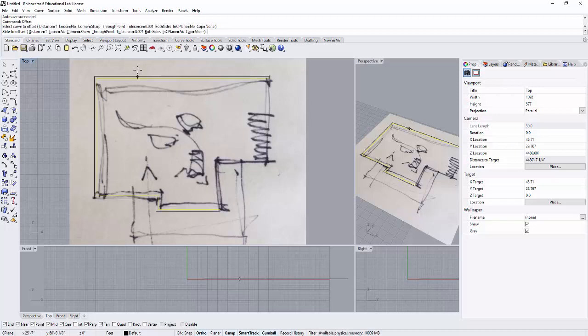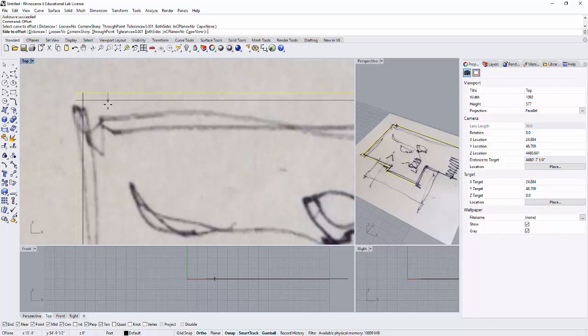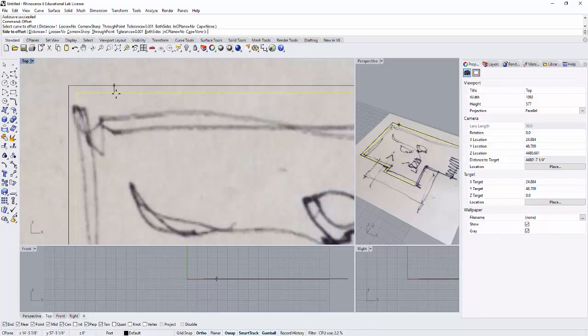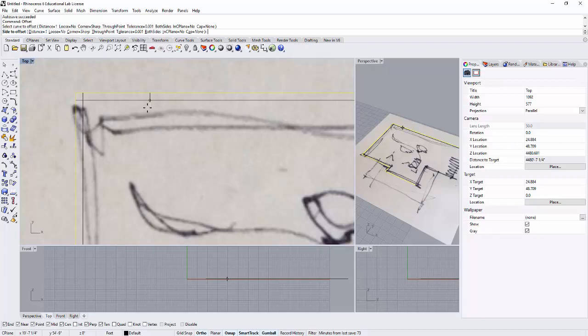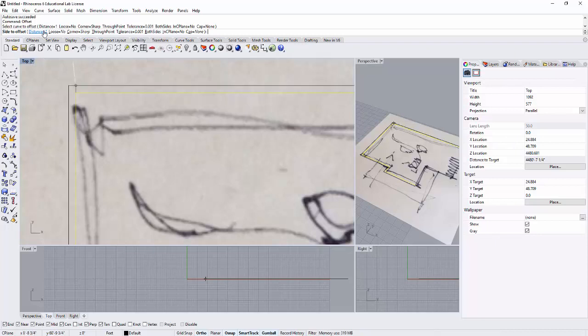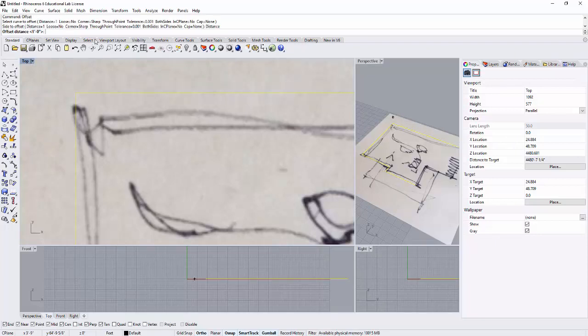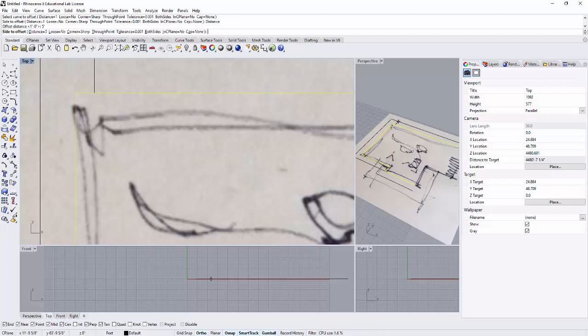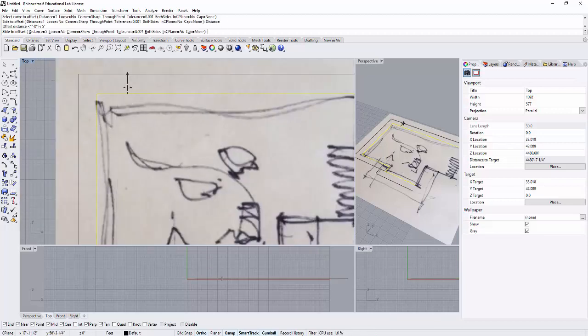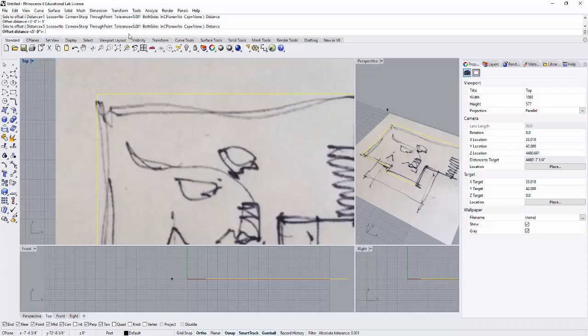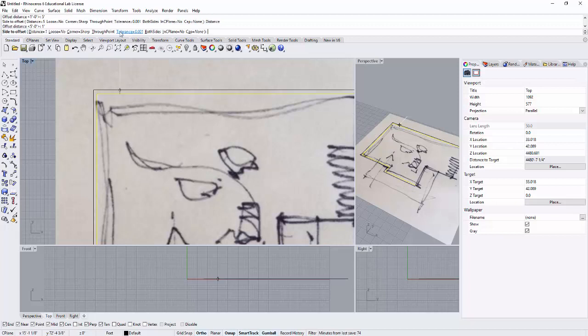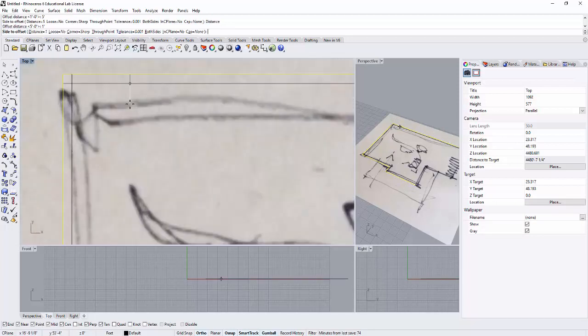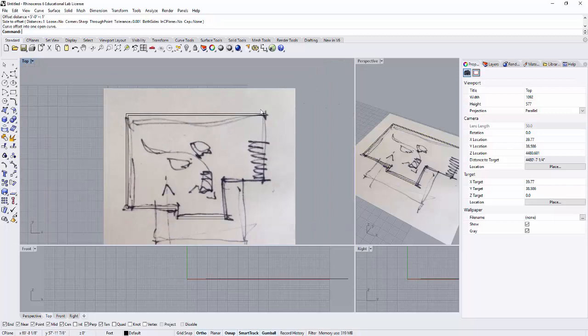You can do it. Once I've selected the curve, it's asking for a direction to offset, either inside or outside. It's also giving me the option to set the distance. If I wanted something other than 1 foot, which is the default, I can click distance here and type in 5 feet, and now that offset is going to be 5 feet. But in fact, 1 foot seems about right. So I'm going to accept that as a dimension and offset that to the inside.